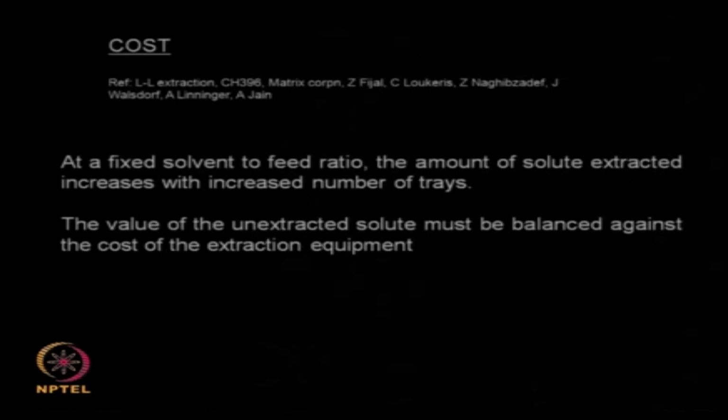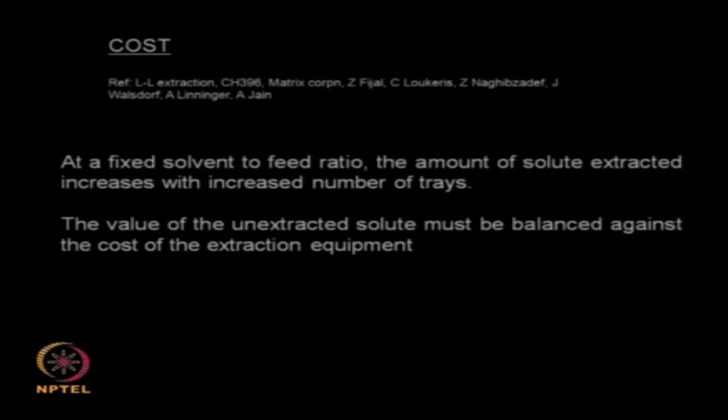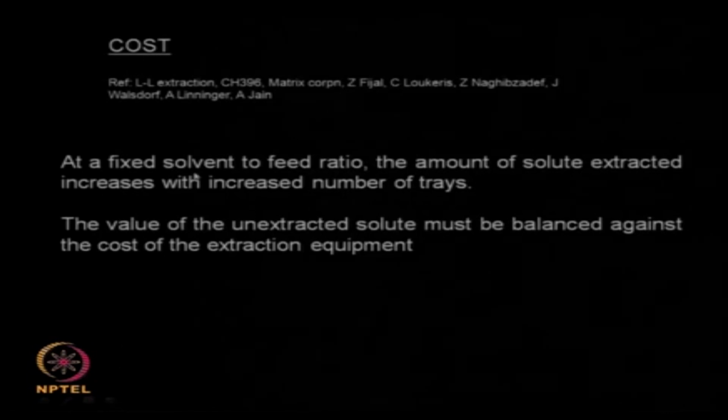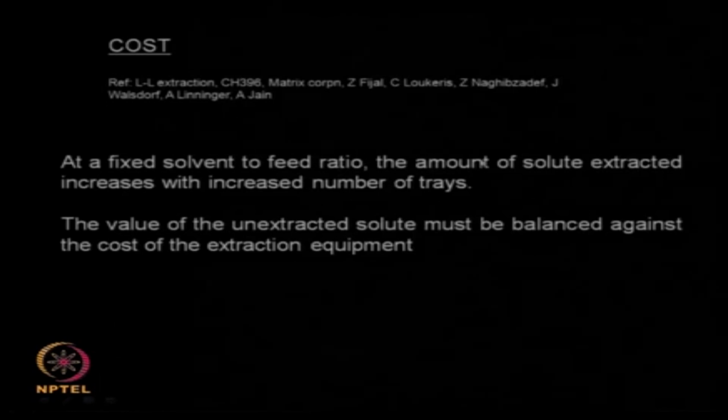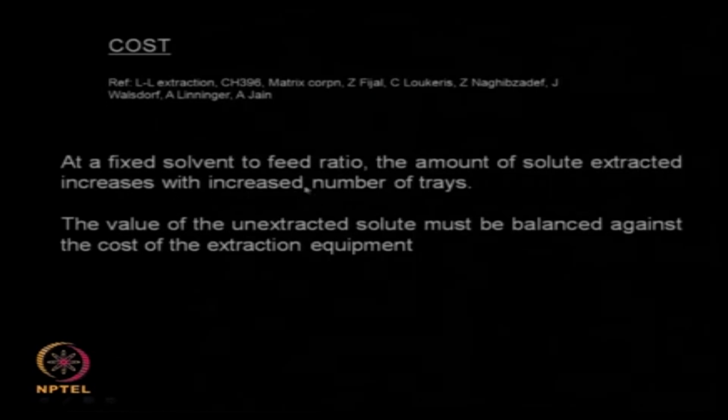The cost data was taken from a book called Liquid Extraction CH396 by a large number of authors. At a fixed solvent to feed ratio, the amount of solute extracted increases with the increased number of trays. So, I am fixing the solvent to feed ratio and I want to keep on extracting.